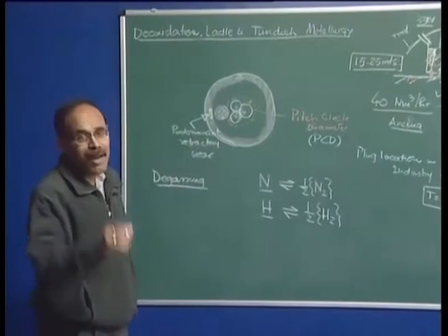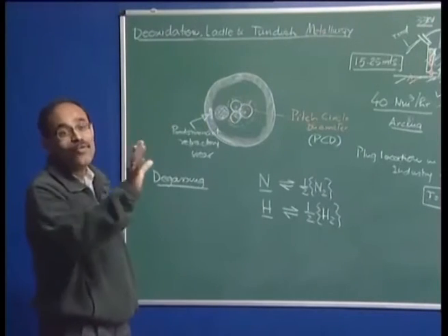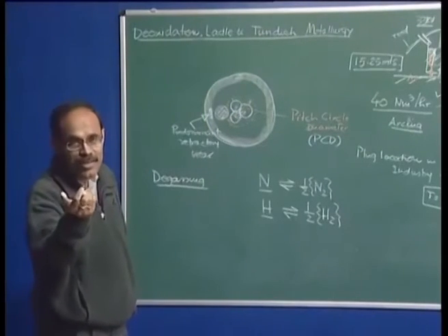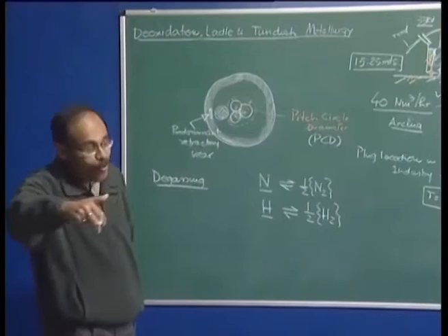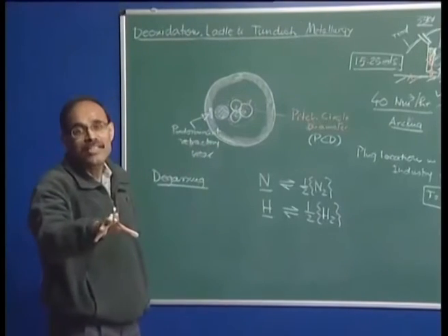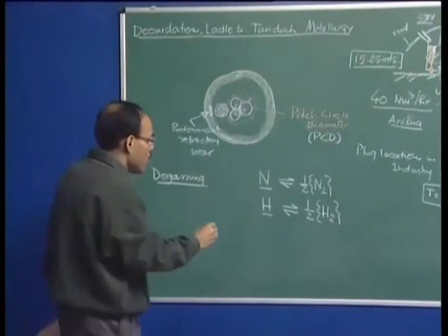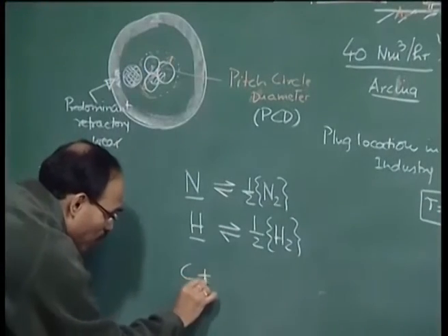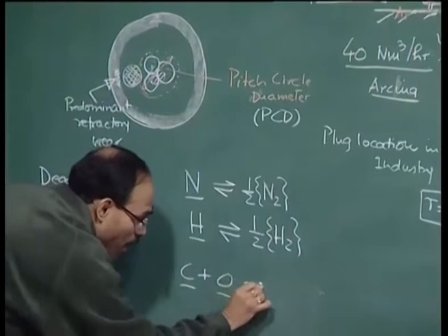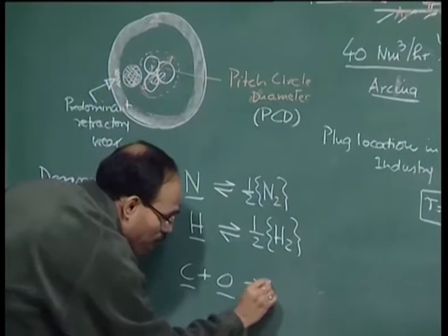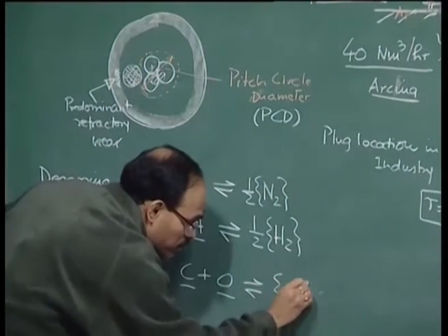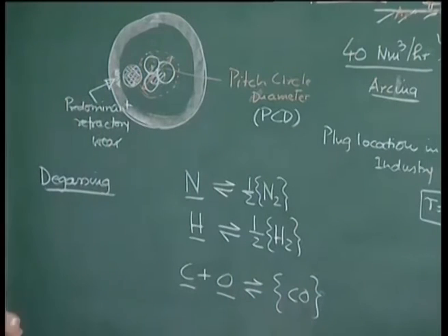We have studied in primary steel making the reaction C plus O is equal to CO at 1 atmosphere pressure, and that curve that is drawn for percentage C against percentage O will shift depending on what the pressure is. So, whatever carbon and oxygen are there in the melt, under the application of vacuum the curve is going to be shifted. So, the CO equilibrium will also shift under vacuum.